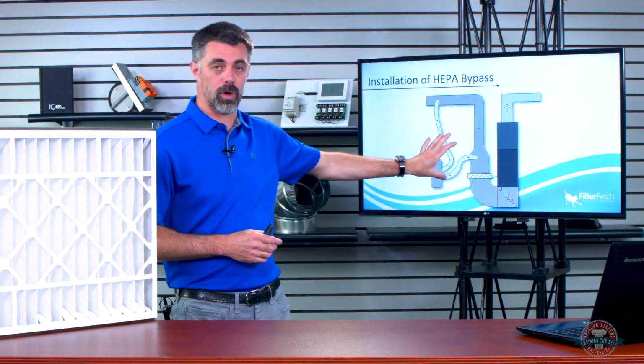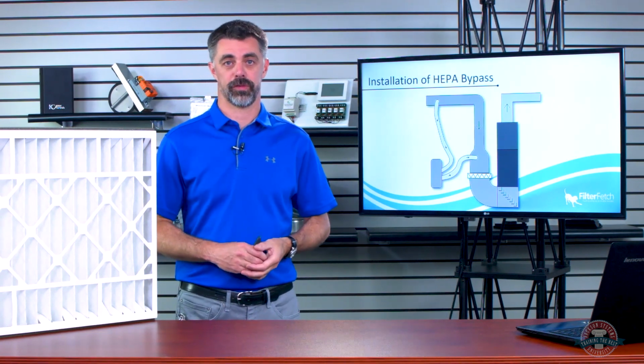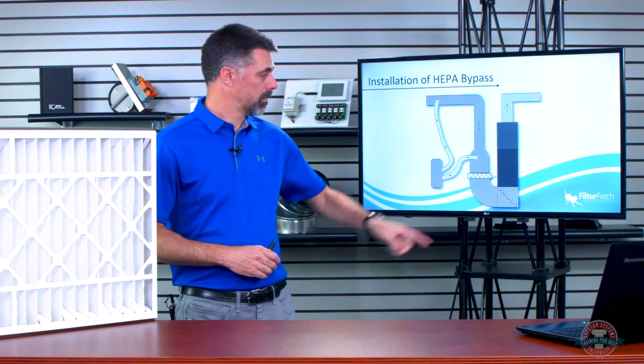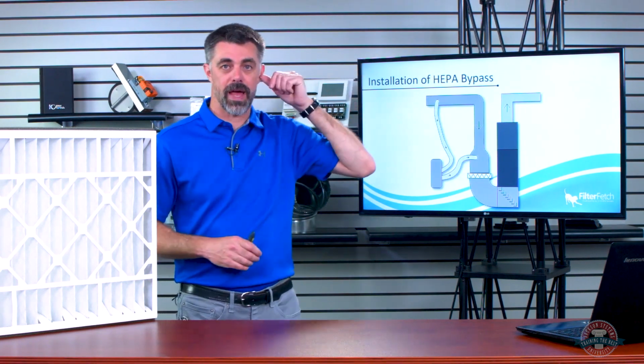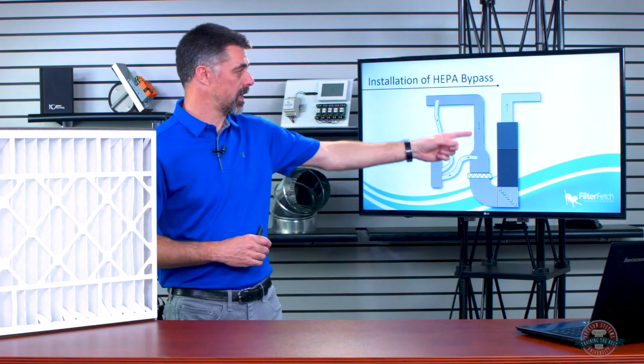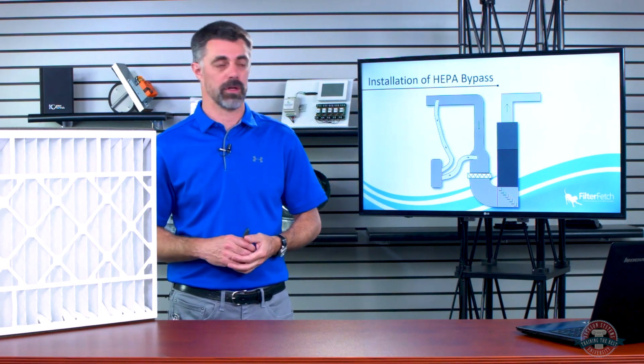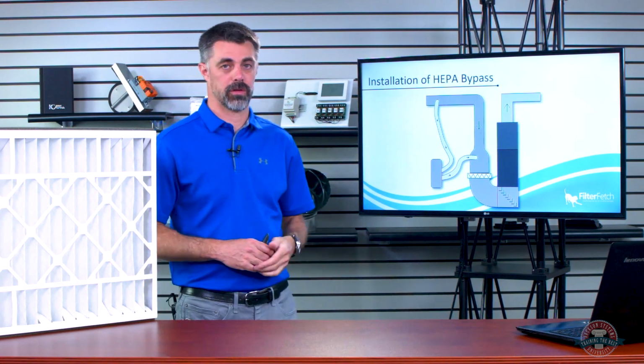If you're going to go to the work to put this in, make darn sure all your ducts are sealed up. You want all these ducts all the way back sealed up, because you don't want any extra dirt coming in there. And if they're in a space where it can get any dirt in, they're going to bring that dirt in there. It's just going to add more dirt into stuff. So make sure all your ducts are sealed up.